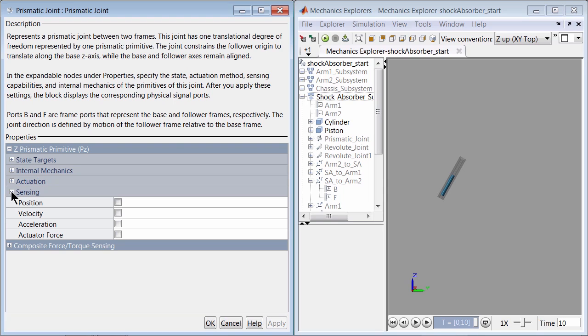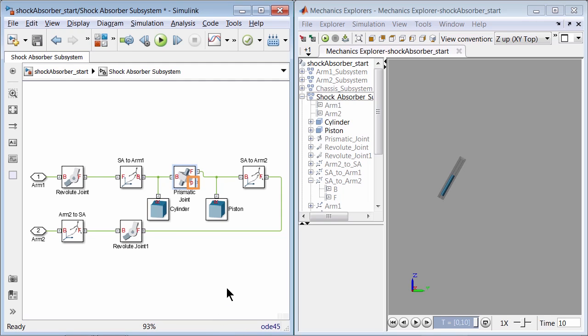These quantities are sent out as Simscape physical signals, which can be used to graphically implement equations for physical components or effects. For our example, we need to sense the position, so let's select that and say OK to save changes to see the physical signal appear here. Now we need to convert the physical signal to Simulink signal so that we can visualize it using a Simulink scope.